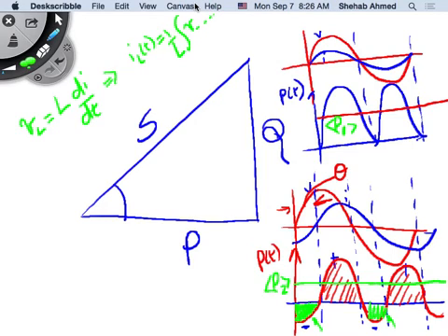So you're integrating the voltage. So if your voltage is very high initially, what does the current look like? Fine, you're going to take bits and pieces of that and integrate and add. So the current will lag the voltage all the time. Even if you have a voltage that's very high right now, and current was 0, what is the current in the next time switching period? You've basically taken a portion of that voltage waveform. Let's say the voltage waveform looked like this, right? You're taking a piece of that and finding the area. Is this the full area under the voltage waveform? No, it's a small area.